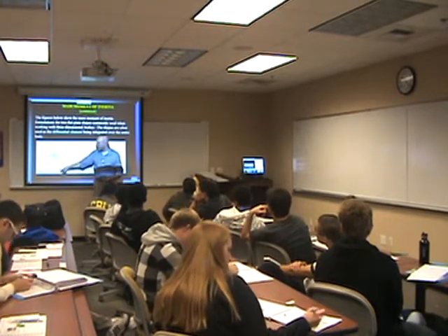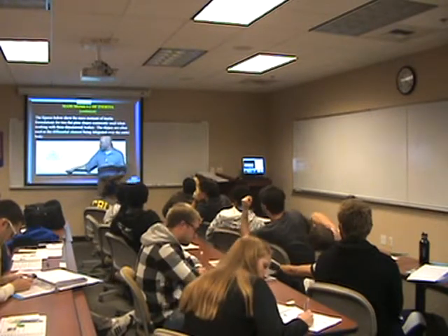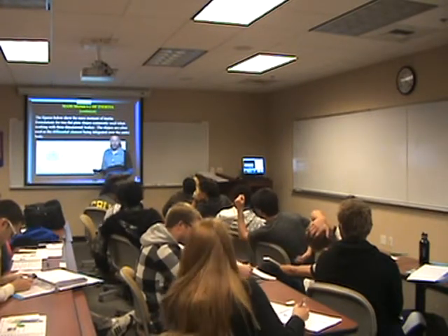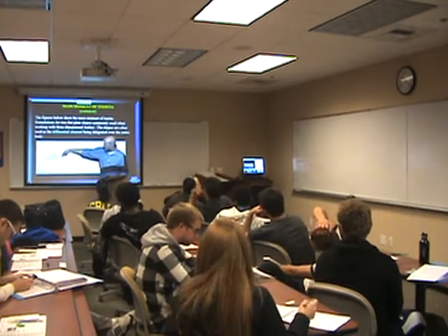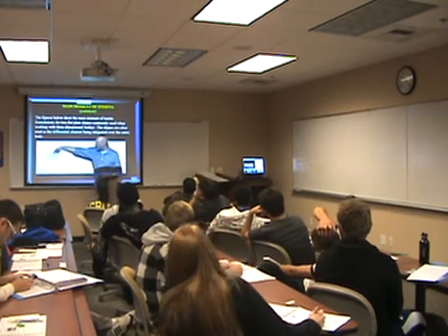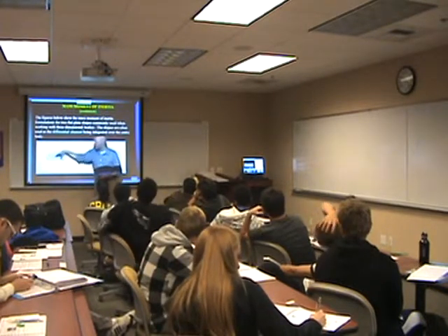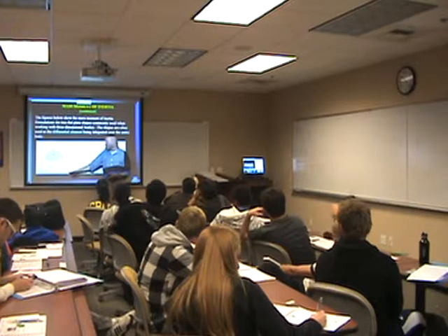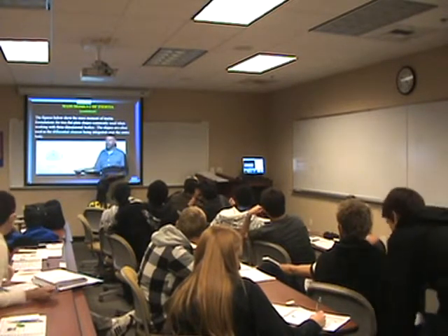And this is like for a wheel, we would typically have a disk that's 1/2 mr squared, I_z'z'. What are we doing now? We're rotating about the end, not about the middle. And that should be the hardest, huh? That's harder because you have more mass further away. And so that's 3/2 rather than 1/2 mr squared.